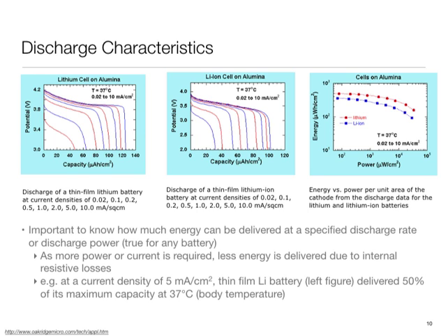And what you see is that the rate at which we discharge the battery affects this characteristic, the net energy I'm able to get out of it. Or another way of saying the following: I take a battery with a certain amount of energy, and if I discharge it with a high current, I will extract fewer joules out of it than if I were to draw a tiny amount of current. Then I can draw more out of the battery.